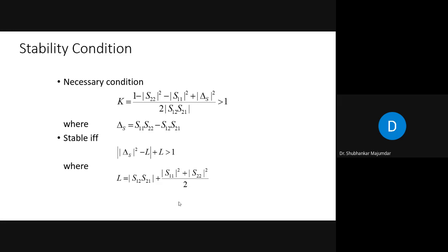So for making the biasing circuit also stable, you need a stability circuit. So by integrating several circuits, you come up with a large circuit which is known as a power amplifier circuit. Getting my point? It means a power amplifier circuit is a system which comprises your power amplifier design, your input matching circuit, your output matching circuit, your stability circuit, and your biasing networks for gate and drain separately. So these all come together to make a power amplifier circuit system.